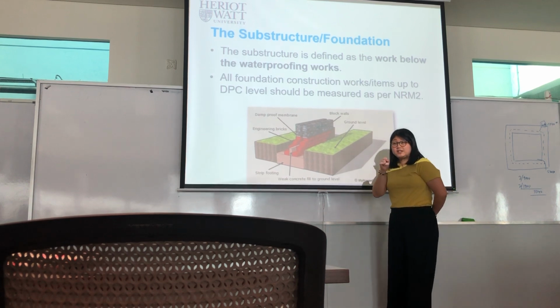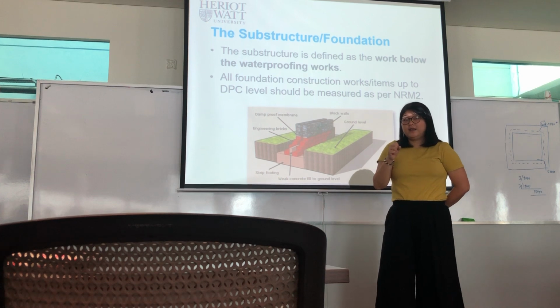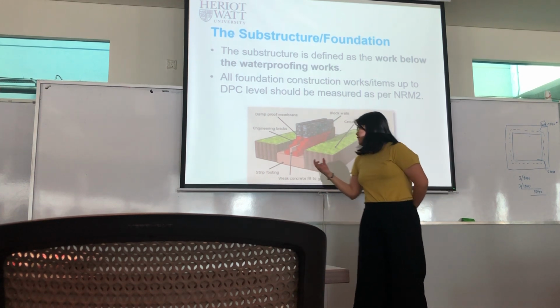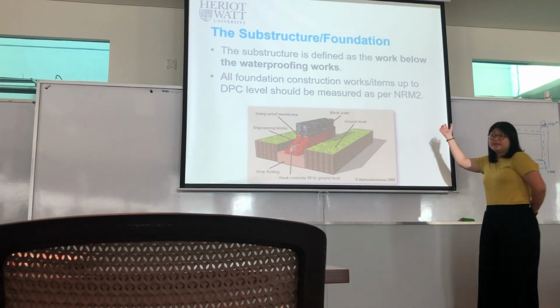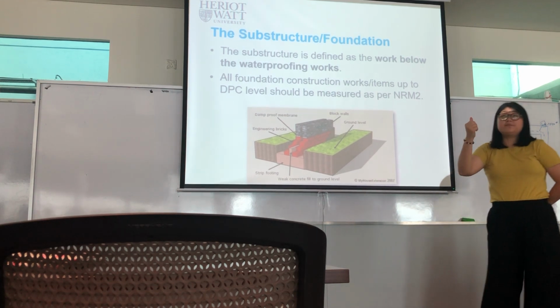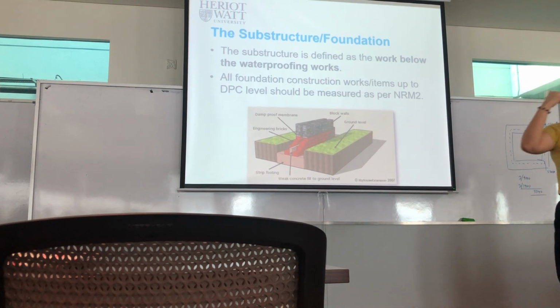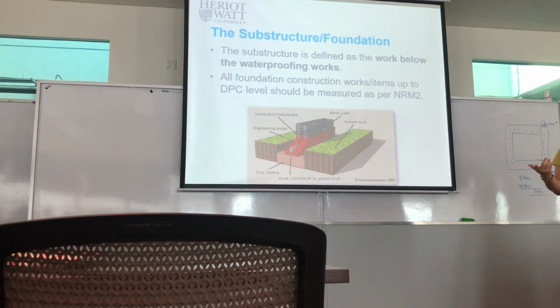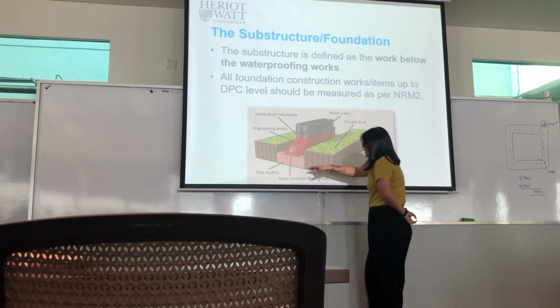Are you disposing your soil off-site or within the site? What is the difference? Off-site means after you excavate, you will send it outside of your site. So the rate is different. Disposal of soil off-site and disposal of soil within the site are two different items that you need to measure separately.